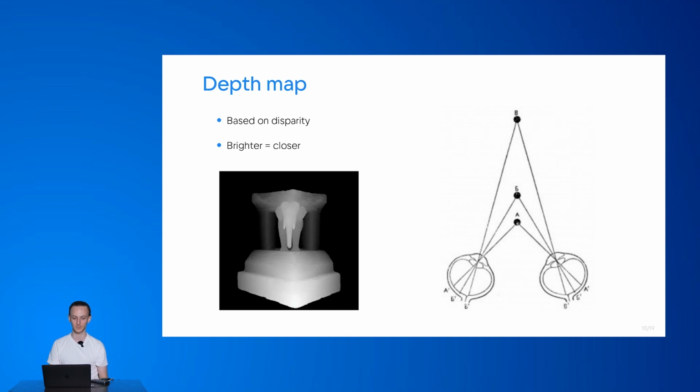The disparity map doesn't give much of that. It's about those disparities that depend on the camera resolution and other things. The depth map works in real measurable distances, so it's a more convenient thing to have. And here on the right, there is a scheme of different distances to the objects and how the disparity is changing.